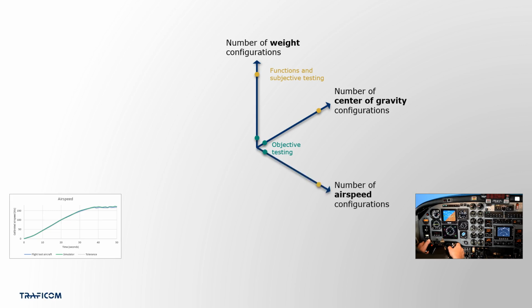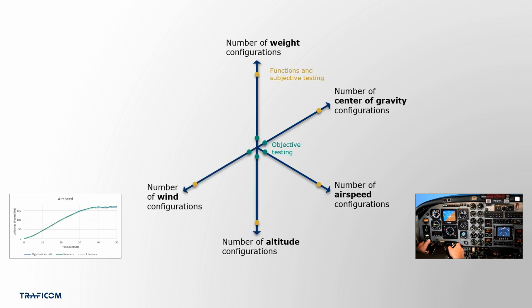Again, the same applies for airspeed and altitude, and for the winds, and for the flight control system conditions. For example, the flap setting, stability augmentation level, fly-by-wire system status, yaw damper state, flight envelope protection functions and their reversionary modes and failures strongly affect the handling characteristics of an aircraft. We could draw even more parameters to the image, but you get the idea already.